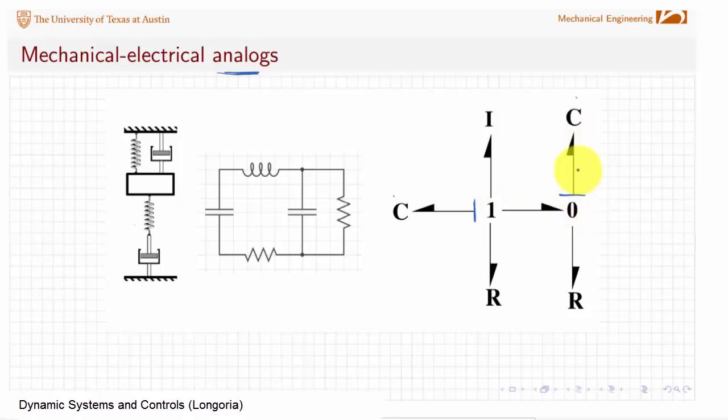Now you've applied integral causality. That's independent. That's independent. Now we've got a 0 with an effort applied from this C, which means both of these bonds better apply flows, right? Now I've completed the causal assignments here. I need to finish with this I element, and because I'm free to specify flow into this one junction, I can apply integral causality here, and then I finish there, and I have the third order system, with the states being the 2 displacement states and the single momentum state.